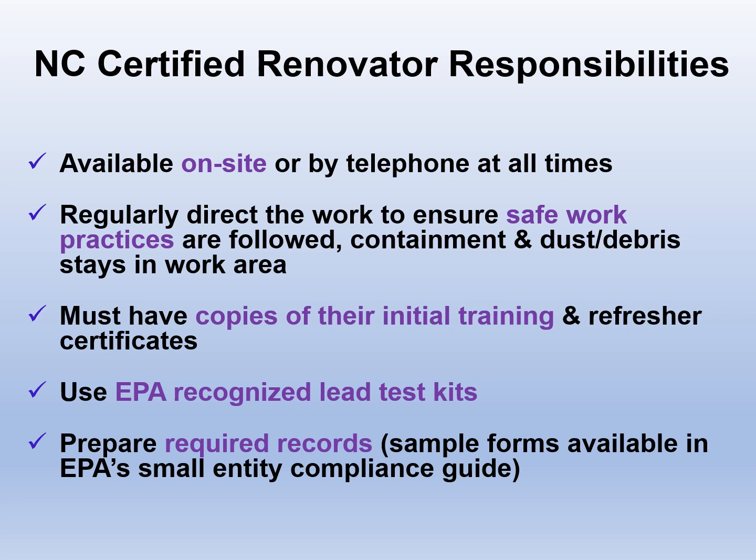They must use EPA recognized lead test kits. They also can use paint chip methods using the heat gun or even the XRF if applicable. They will prepare required records, and such sample forms can be available in the EPA Small Entity Compliance Guide booklet.